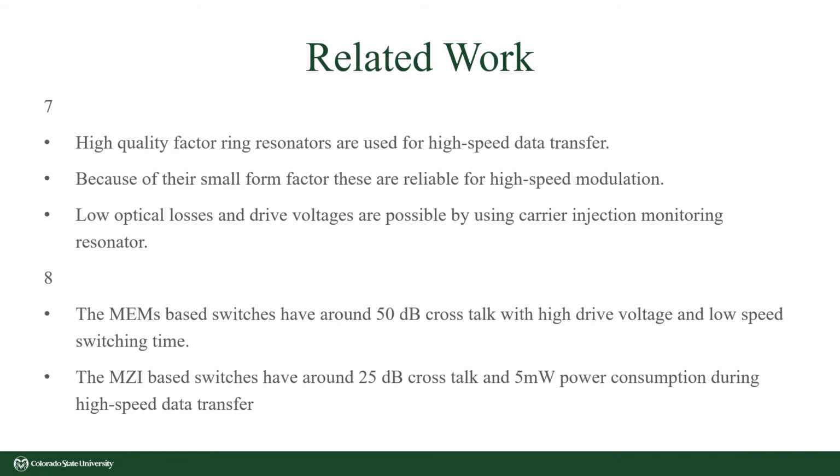Next, to design optical switches for high-speed data transfer, high-quality factor ring resonators are used. These ring resonators are reliable for high-speed modulation and high integration due to their small form factor. Low optical losses inside the cavity and low drive voltages are possible by using a carrier injection micro-ring resonator. With this method, effective switching for the signal at high speeds can be achieved with low drive voltage.